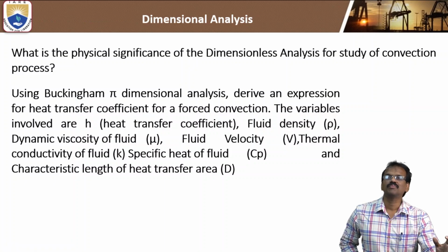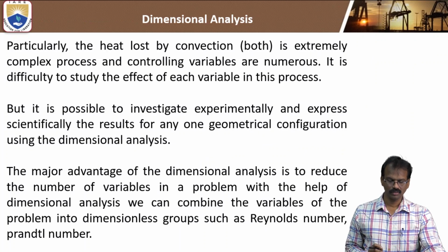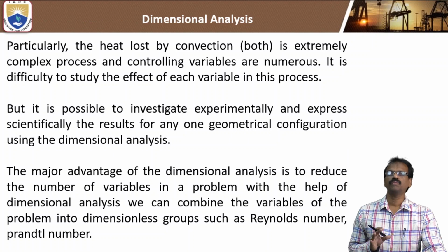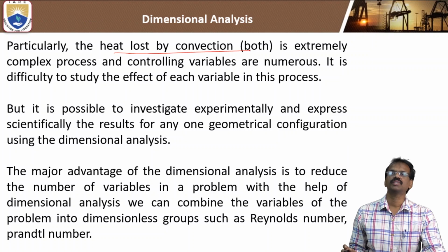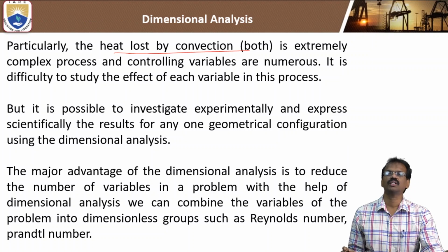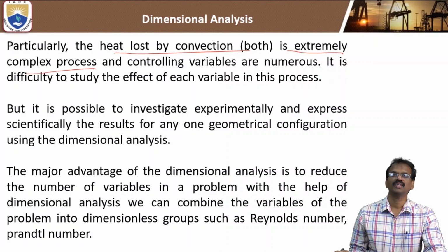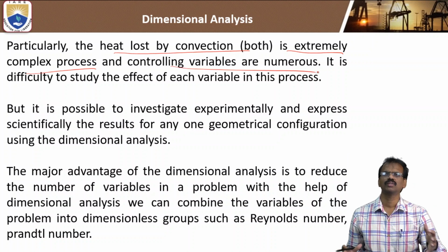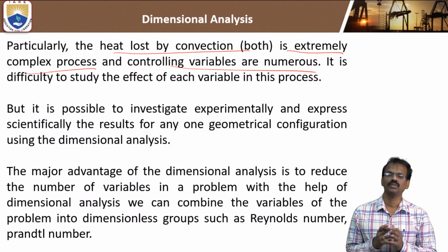First of all, we will see what is the importance of dimensionless analysis. Why you have to study about dimensionless analysis. In last class we already discussed this. Studying the convection process, particularly heat loss by convection, both natural convection and forced convection, is an extremely complex process and the controlling variables are numerous, because convection takes place only in fluids.